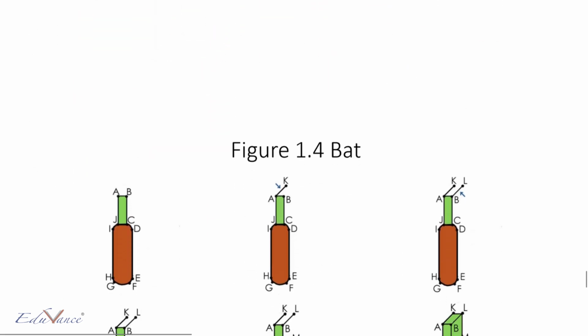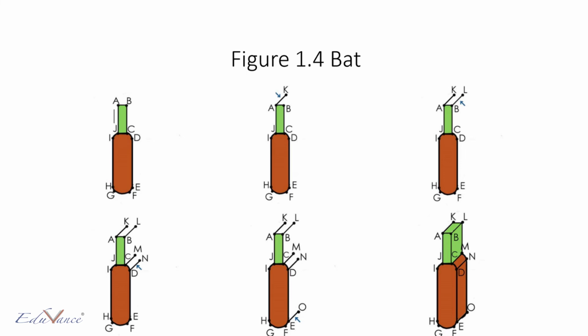So let us look at another example. This example is a little more interesting. We shall see why. I start off with my points A, B, C, D as before. I extend the points depending on the depth. I take all these points and extend them. Now, once I extend, I want you to watch what I'm doing very carefully. I first connect all my straight lines.